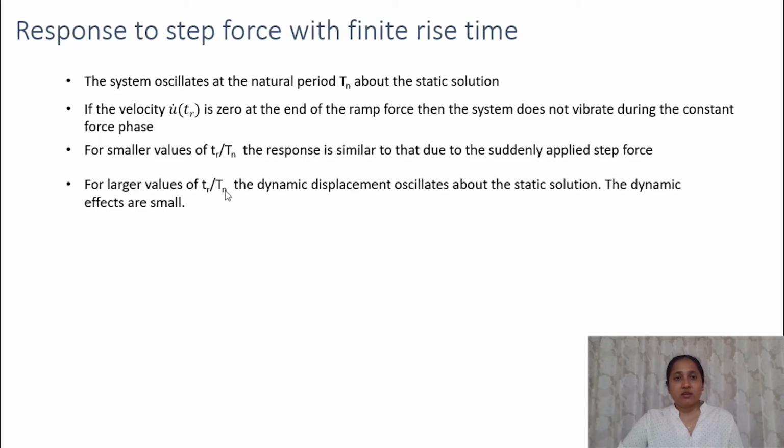When Tr by Tn is large, then the dynamic displacement oscillates about the static solution and the dynamic effects are small. So if you have a large rise time, then the dynamic effects are small, but the structure will oscillate about its static response position.